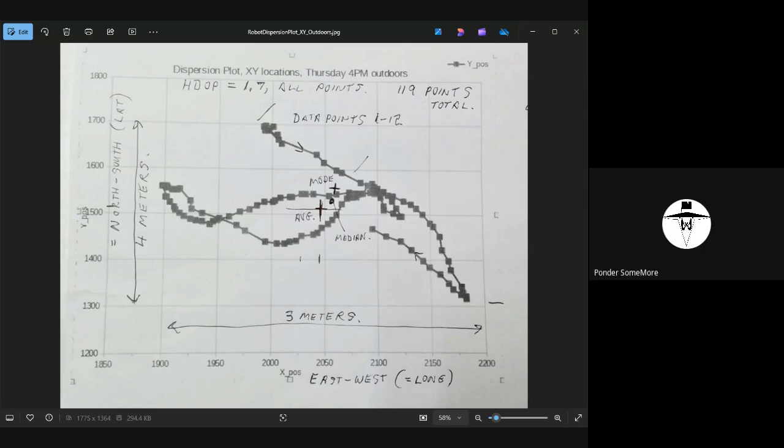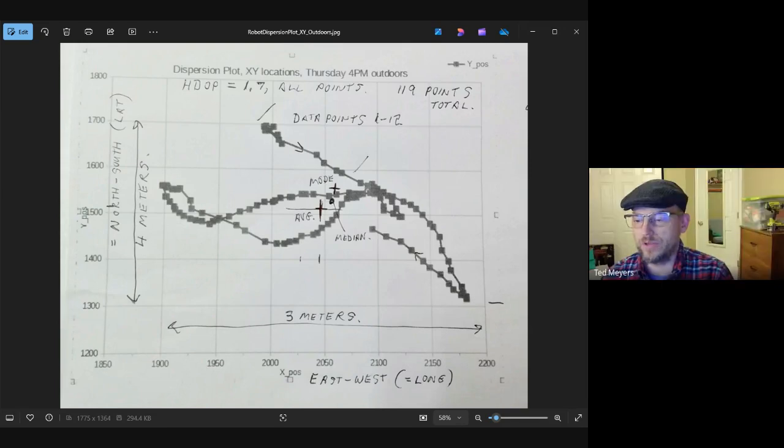Yeah, but over large distances of movement, you can get an average heading change that's pretty accurate. It's just that how much distance you have to travel is related to how precise your signal is. Right. And putting 2 GPSs on one robot that are separated by less than a meter wasn't sufficient, at least for him.